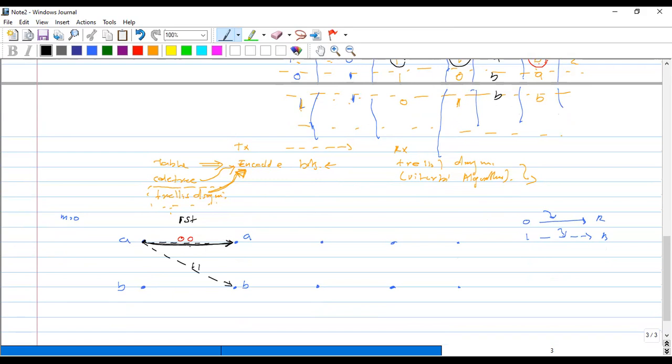So at the first clock cycle, we will have two options, if the input is 0 and if the input is 1. Now when we go to the second clock cycle, if you are in A and the input is 0, you will move to status A again and output will be 0, 0.